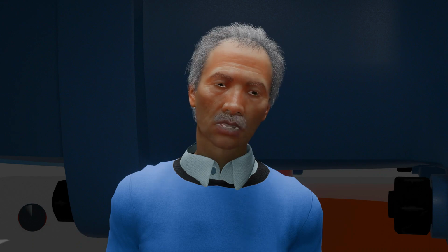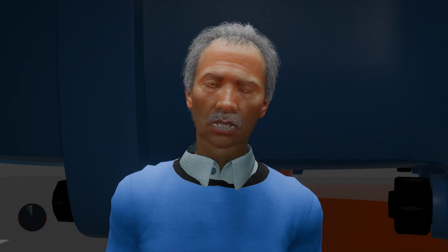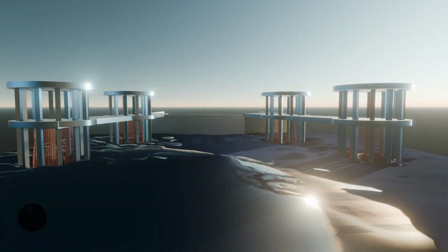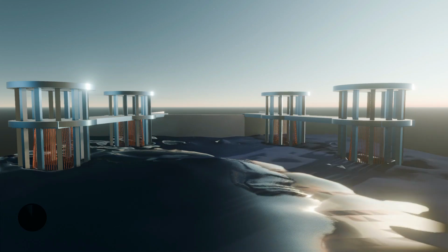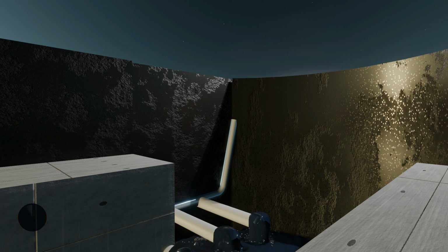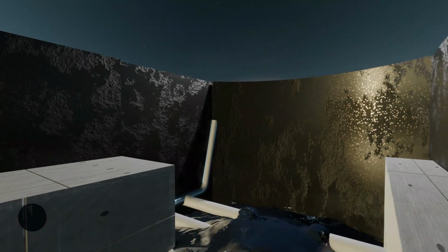Again, the reason why the intake is designed that way is to prevent debris from being collected at the base, thereby blocking off the flow path to the penstock. While the penstock is usually constructed using a steel line. The reason why steel line is used is to prevent weathering in the long run.